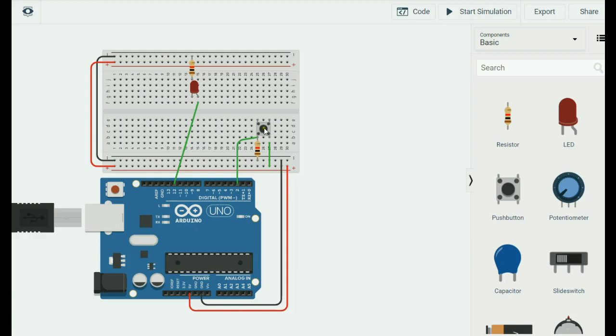So we press this button, 5 volts from here will flow through this wire to this input. So this will be a way to detect that the button has been pressed. You don't press the button, then this power is not connected here. You press the button, then this power is connected here.